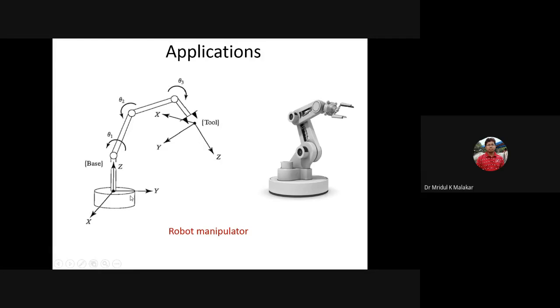So you have to calculate and find the dynamics of the system accordingly. You can design a complex or adaptive algorithm so that it can, suppose, serve your tea. Design one program, write what kind of motor you will use, you have to select. It is simply a hinge joint, and the angular movement is theta 1, theta 2, bidirectional theta. So definitely we have to use a stepper motor, or a servo, which is cheaper than a stepper motor, so we can go with the servo motor, and you can design the smooth control system.